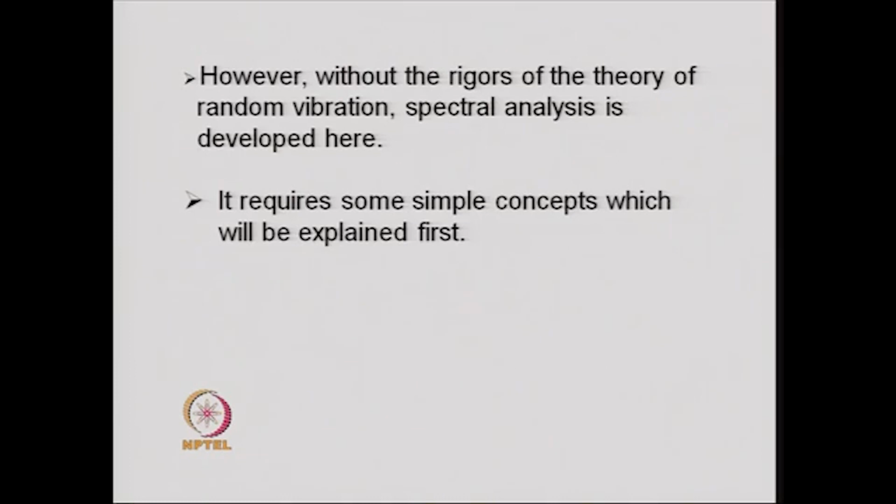We will take up only a portion of the random vibration analysis, which is known as the spectral analysis, and using that spectral analysis we will try to obtain the response of the structures for future earthquake modeled as a random process. The spectral analysis is quite elegant, simple to understand, and provides us a very good estimate of the peak response and the root mean square response of the structure.